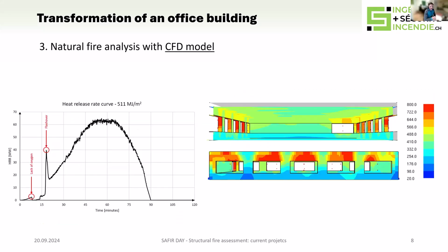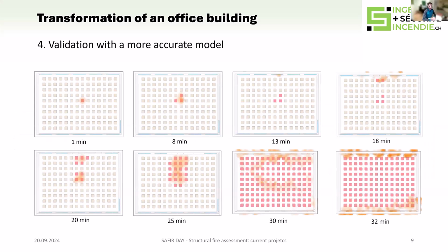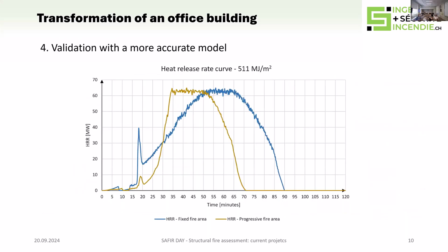As we see, the behavior is quite good and the temperature will not rise too high. And for the second model, we did a more complex FDS analysis. We put some wood blocks and ribs all over the compartment, and we have something that looks like a traveling fire. And at the end, at 30 minutes, we have a fully engulfed fire. So we have the highest temperature. You can see here the two models are quite similar, but the fire development is not the same.